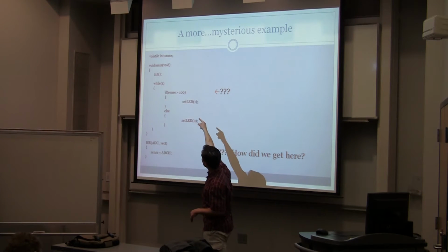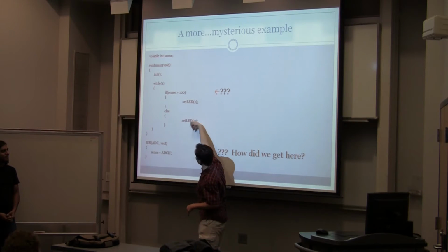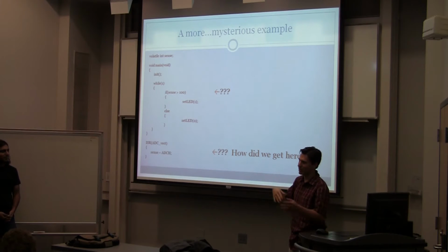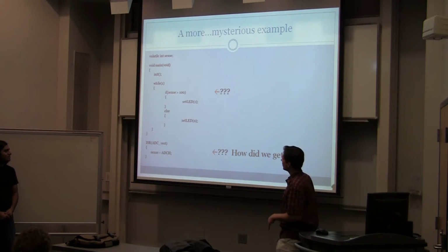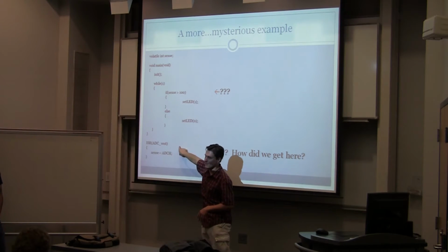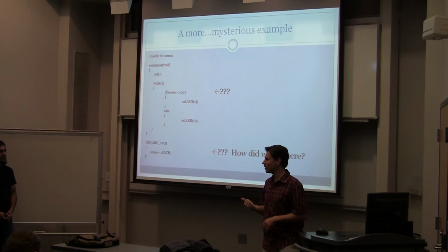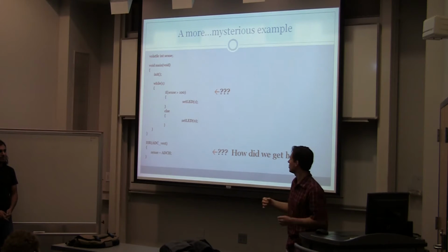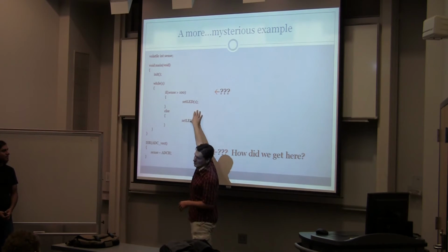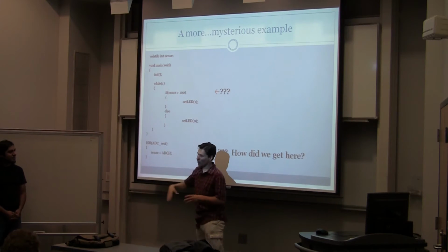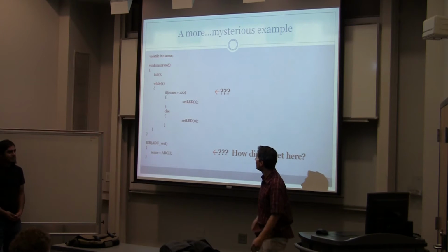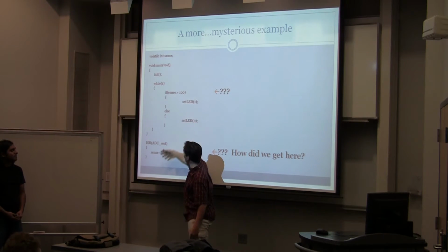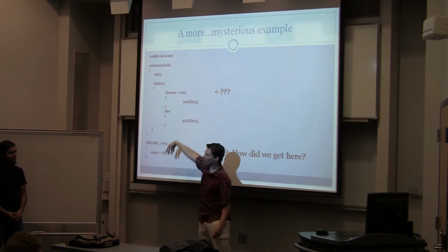So you have a main, you do an initialization, and then while one, if sense is greater than 100, set the LED, otherwise set the LED to off. Now, the interesting thing about this is we've never set sense to anything. We didn't say sense equals read analog. So what's happening is there's this special function here, which is an interrupt service routine. And it fires every time the analog subsystem says, I've completed a conversion, there's a new value in my register. So you can think of this as happening asynchronously from this. So this is just getting fired whenever the analog function says, hey, I've got a new value. So when that happens, you set sense to the analog value, and it gets updated. And so if sense is greater than 100 one time, you set the LED, otherwise you set it off.